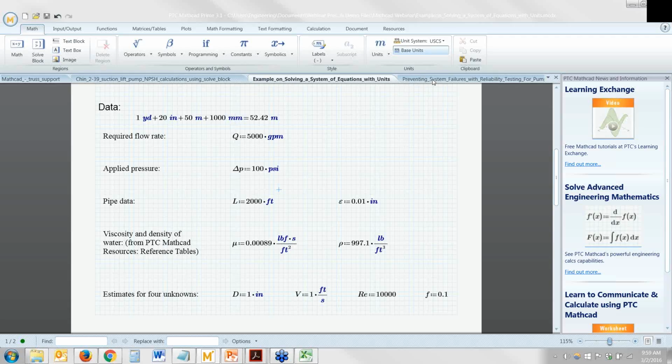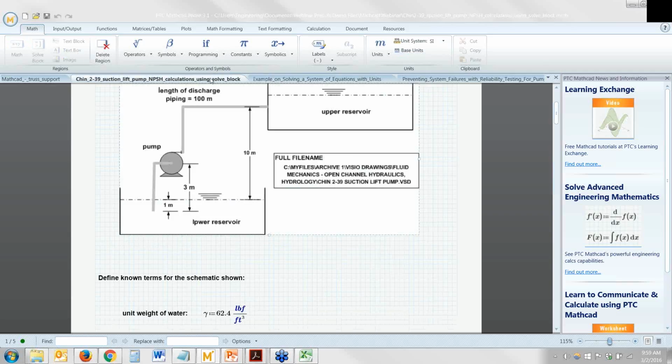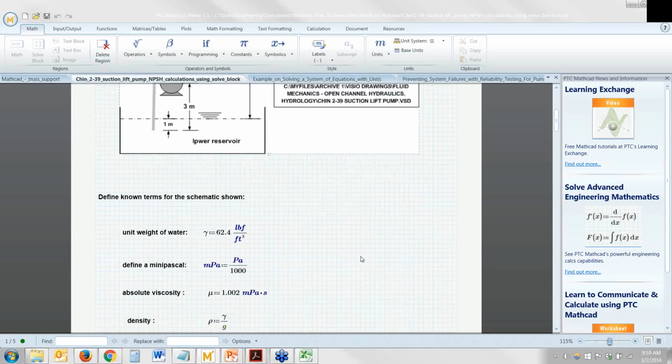Now, the next thing we'll go into here is we'll flip back one level. I just showed how you can use all those different units in Mathcad and work through those calculations. Well, what happens if you have your own units? Mathcad has pascals for units of pressure. It doesn't have millipascals. What happens if we work in such minute quantities that millipascals is very helpful, and we use that a lot? Well, we can go ahead and define from Mathcad what our units should be.